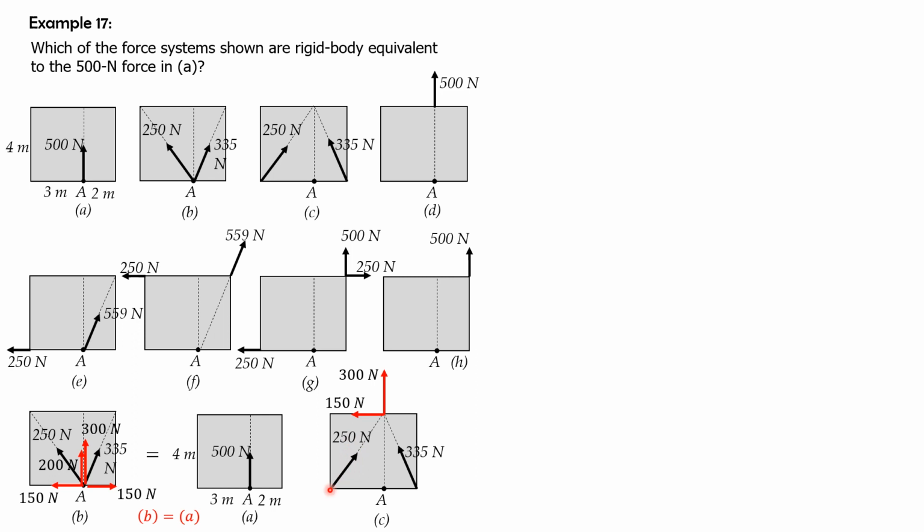The horizontal component of 250 is 250 times 3 over 5 rightward. You can move the components of this 250 force here on its line of action by principle of transmissibility. So this 150 will just vanish. So it will be 0. The vertical component of 250 is 250 times 4 over 5. You can move it here, so it's 200.